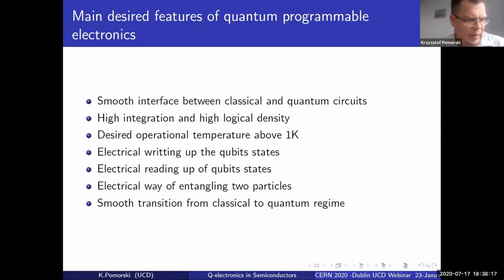If you have a traditional superconductor, then you have a so-called superconducting coherence length, which is usually like 3,000 angstroms in Pb. This simply means it is like 300 nanometers, and you cannot go to smaller sizes. So there is an obvious limitation in the size of Josephson junctions, and this is one of the obstacles in development of highly integrated circuits.